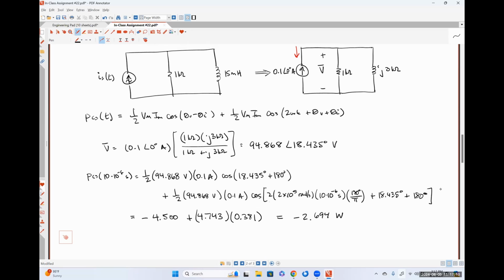Although we do also know voltage. So I would argue that we do know the voltage across the resistor, and we do not currently know the current flowing through the resistor. We could get the current by using current division, but that's overkill since we already know the voltage, right? Because all of these elements are connected in parallel, the voltage is common to all of them.